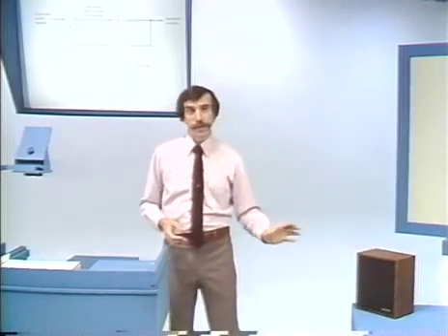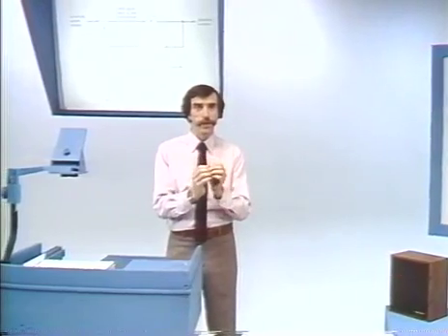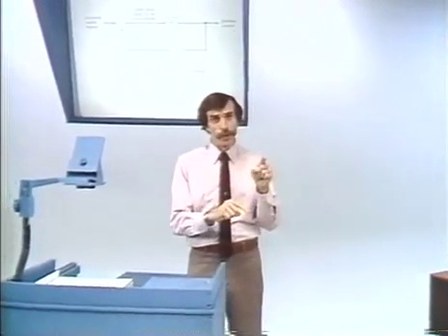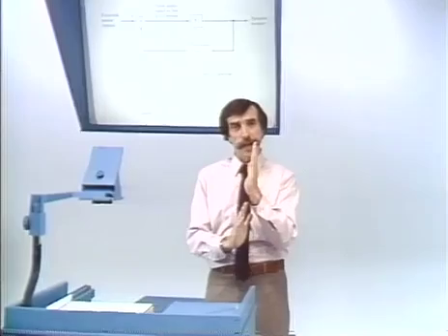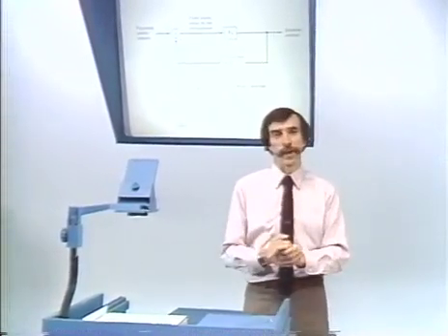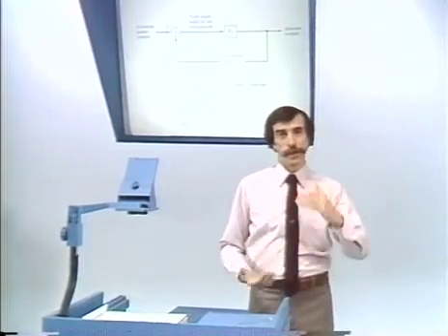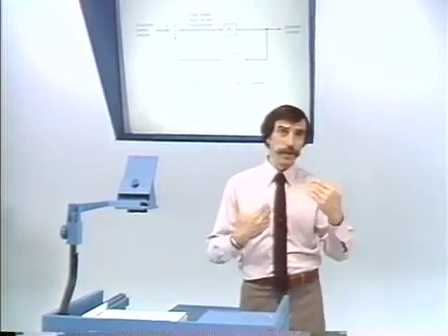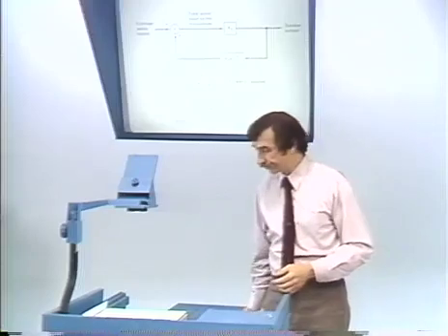If we can just turn the speaker off now, you can see that as K2 increases, the poles are moving onto the j omega axis. The system starts to oscillate. They won't actually move into the right half plane because there are nonlinearities that inherently control the system.